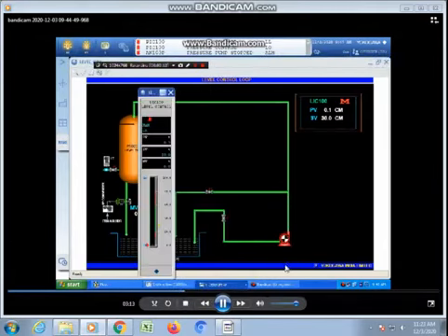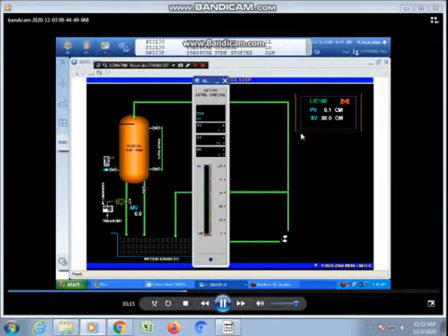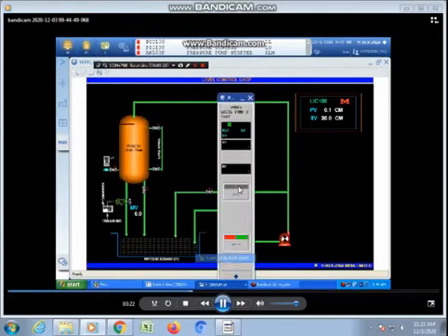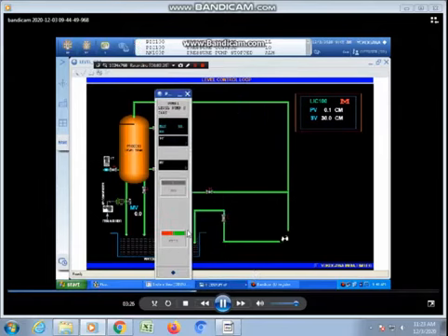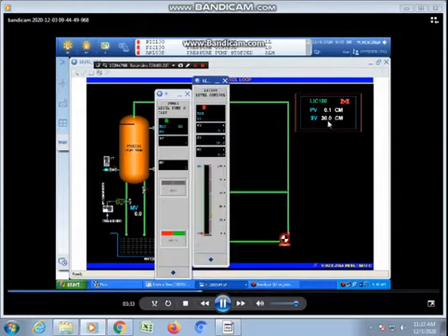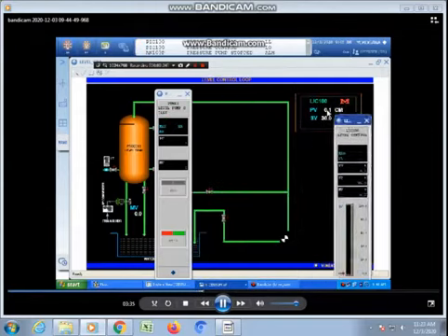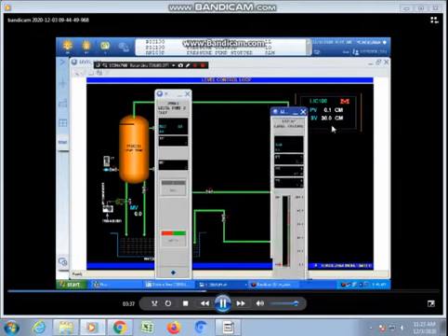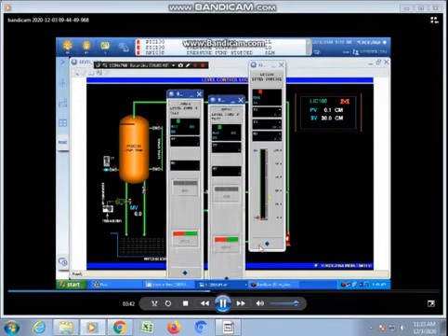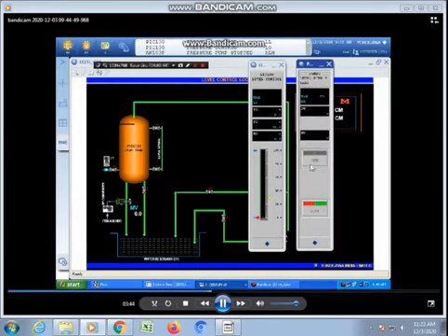the pump. So we will double click this LIC 100, that is level indicator cum control, and we are taking the pump. So both things are there. One is we have to switch on the pump, another one is we are going to see the control operation of the process. So you can see we have a PID controller faceplate, we have a pump controller faceplate.